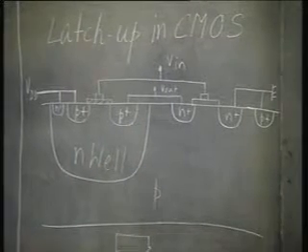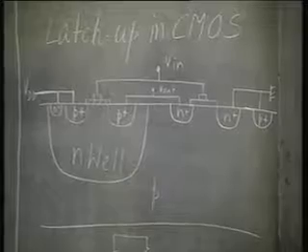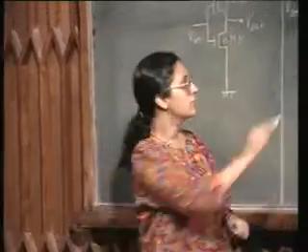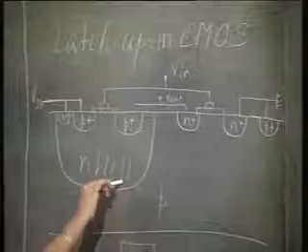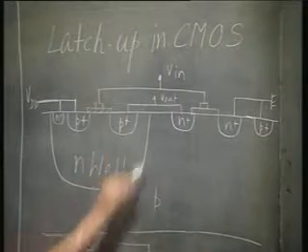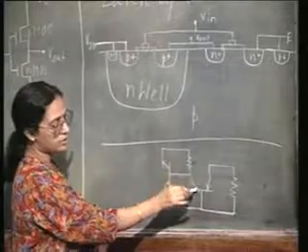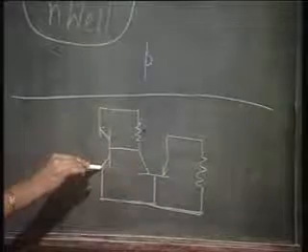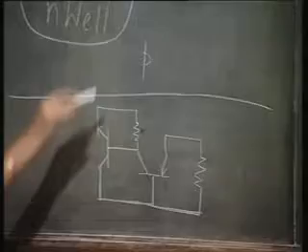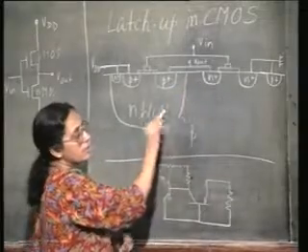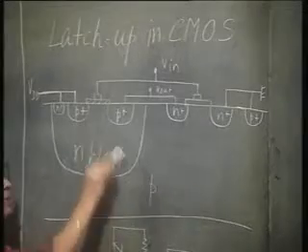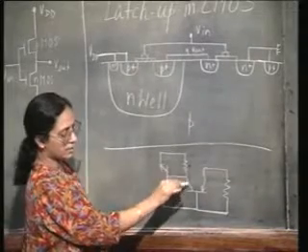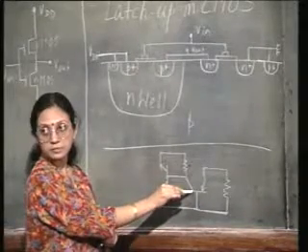Again you see these two transistors are, you could say, sort of merged together, right. The PNP transistor base is actually the collector of the NPN transistor, and again you see the NPN transistor, the base P is actually the collector of the PNP transistor, right.